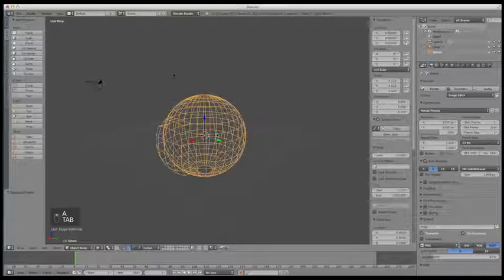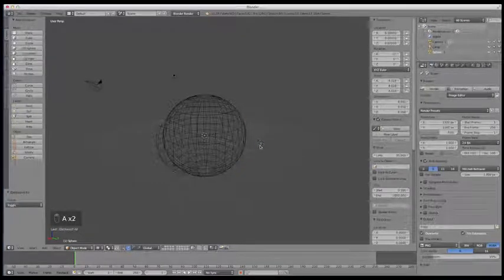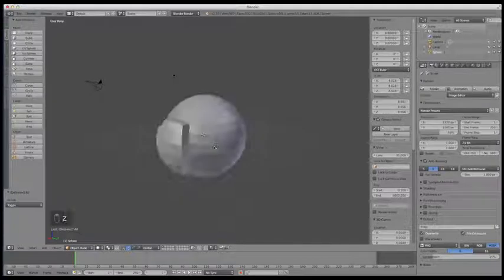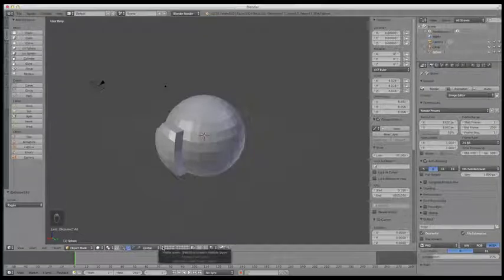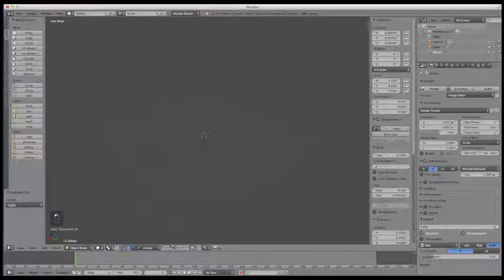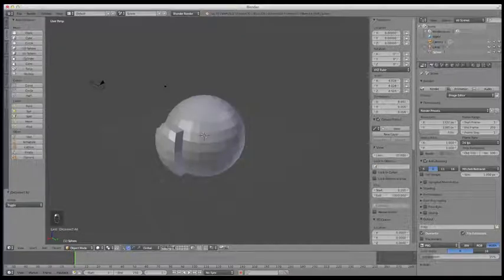So pretty handy there. You can also move objects in your scene onto what are called layers. By default, you're put on the first layer, which is down here at the very bottom of your viewport. You can see this little box that's checked, and then there's a dot in it. That dot means that there's something on the layer. By clicking on these buttons, you can change what layer is currently visible. It also works by shift selecting if you want to select more than one layer. If you never mess with layers, you're only ever going to be working on the first one.